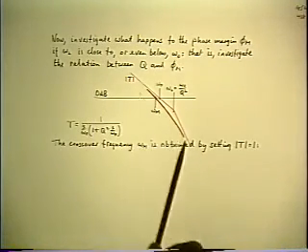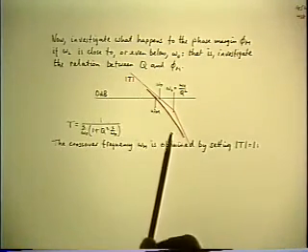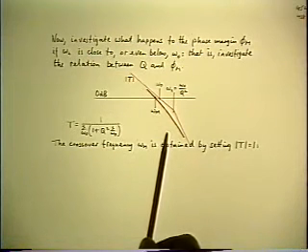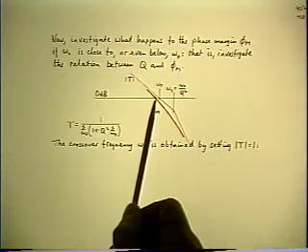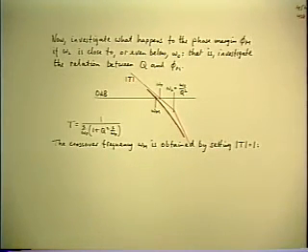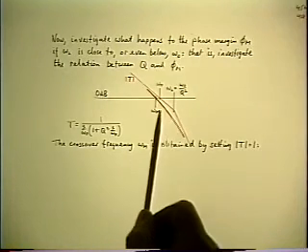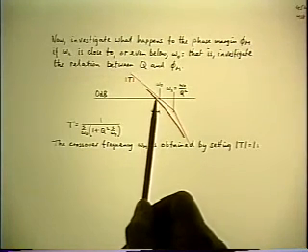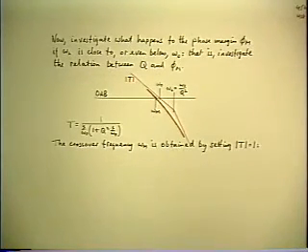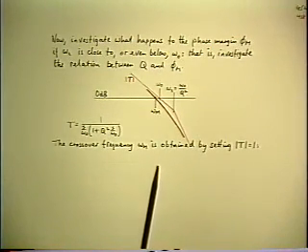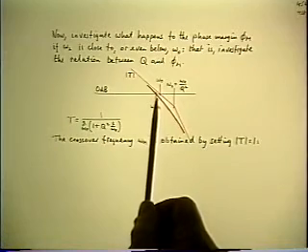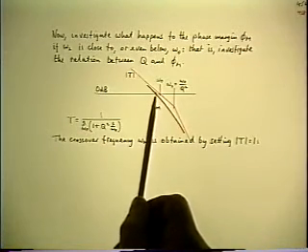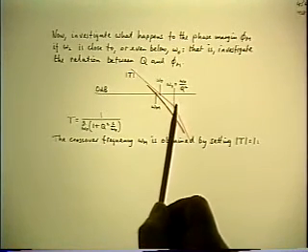In other words, the smooth corner is going to move through the axis, and the crossover frequency is really the frequency where the actual curve crosses unity magnitude, not where the asymptote crosses. So omega m is the true crossover frequency at which we want to evaluate the phase margin. So the first thing we do is evaluate the crossover frequency in terms of the position of the second pole.